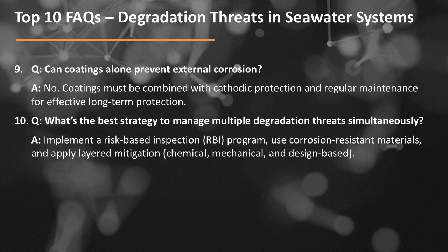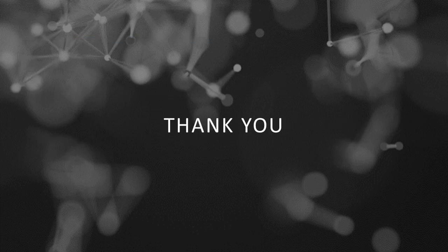Question number 10. What's the best strategy to manage multiple degradation threats simultaneously? Answer: implement a risk-based inspection or RBI program, use corrosion-resistant materials, and apply layered mitigation: chemical, mechanical, and design-based.